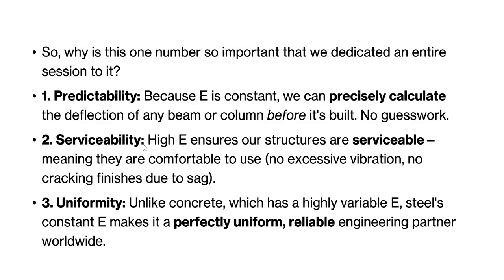Next comes serviceability. Higher E ensures our structures are serviceable. What are the serviceability criteria? Deflections and cracks and all are called serviceability. So the higher the E, the more the material stiffness, and that gives more serviceability, right? More life, meaning they are comfortable to use. No excessive vibration, no cracking, no cracking of finishes due to sag.